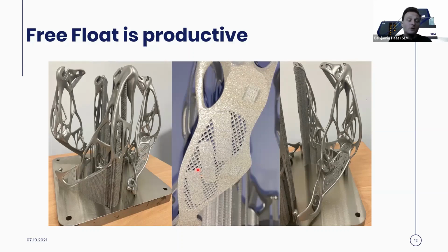Depending on the actual part requirements, it depends if you would like to use this part as it is, or if it needs surface finishing anyways, because you really have high surface requirements. It's quite important that the roughness that you're seeing on one area is somewhat comparable throughout the entire area, because this then makes it easier for post-processing. And this is exactly what we achieve with this part.